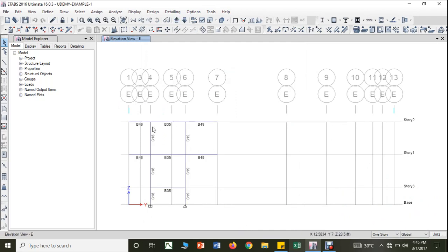Whenever the earthquake happens, due to the earthquake forces, the structure will try to move in both directions. At that time there will be a chance of failure of these columns. So what we will do is connect these two by a member called a damper. In dampers you have various types, which let us not discuss, but usually they will provide these two joints with the damper in the middle.